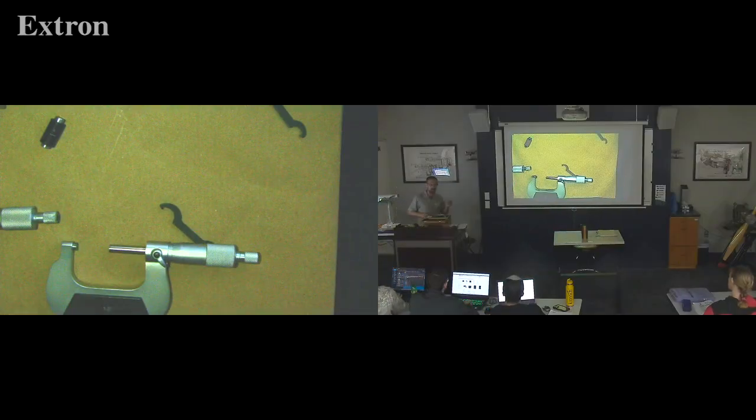But what's happened is when we get to recip engines, I wish I had a quarter for every time a student said, the micrometer was on, and all my measurements are smaller than they're supposed to be. So then I go and grab a micrometer out of another box, sit down, and I calibrate it. And then I go over there and measure it, and I'll say, huh, it's within limits. No, it's not. Let me see that. Oh, I had the thing set wrong. I mean, it's been dozens upon dozens of times. Okay? If the measurements are not right once or twice, don't keep doing the same thing expecting the same results. There's another name for that. Okay? Insanity, yeah.